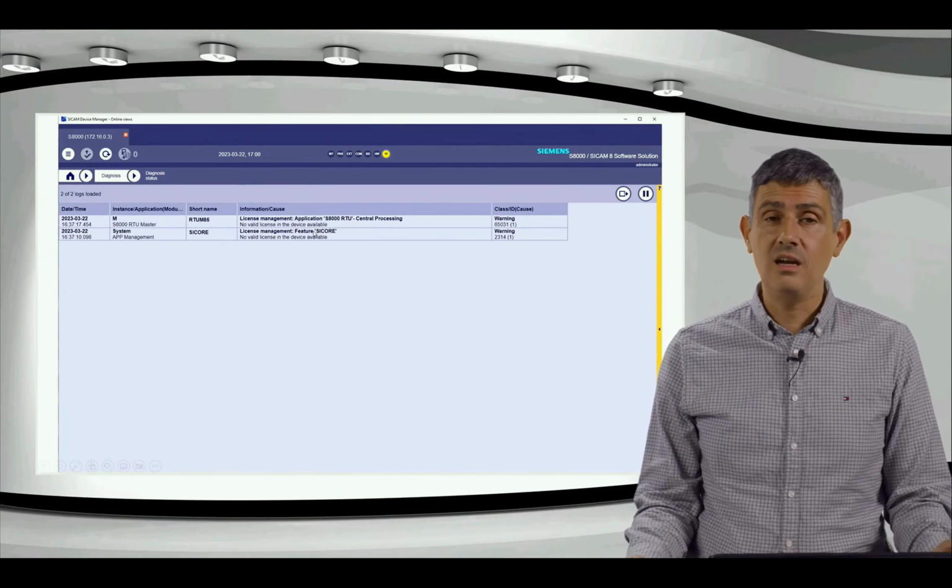Once we do that, then we know that for this graphic that we just created, we have here the drawing board where we can create our single line diagram. So we will need to draw here and include some symbols, which we can find here under single line elements. Under single line diagram elements, we will find specific objects for substation automation, for example. And everything works here via drag and drop. So if we want an object, we select it, drag it, and drop it where we want to place it.